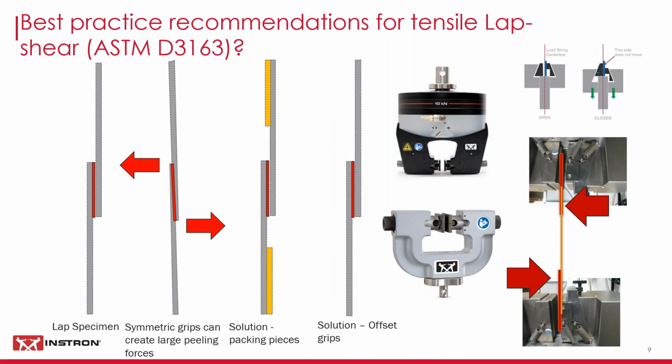We design and manufacture our own load cells, and they're all specified for this kind of operation. So we have specs for the effect of small offsets on accuracy. And basically, small offsets will not affect the accuracy to any degree, or the reliability of the load cell.